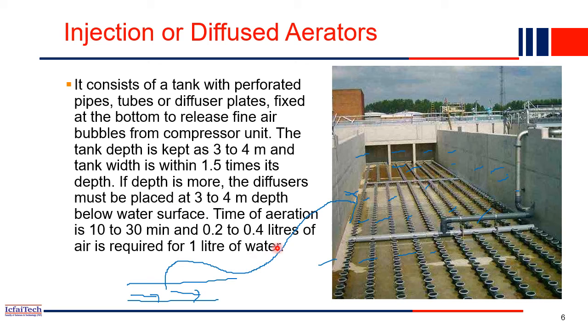So basically water will percolate through it, and it absorbs. If the depth is more, then the diffuser must be placed at 3 to 4 meter depth below the water surface. The time of aeration will be 10 to 30 minutes. The total water will be resting in this chamber for 10 to 30 minutes,